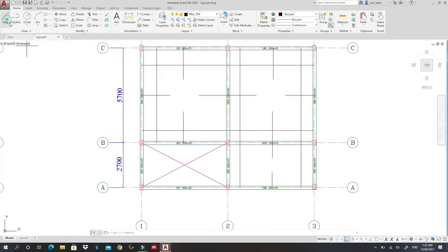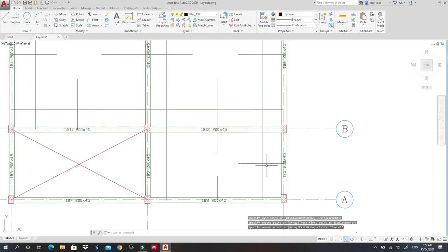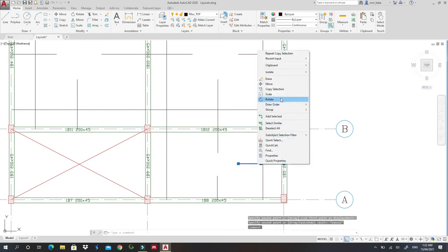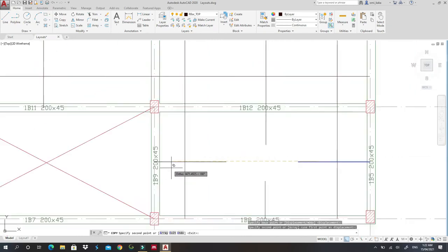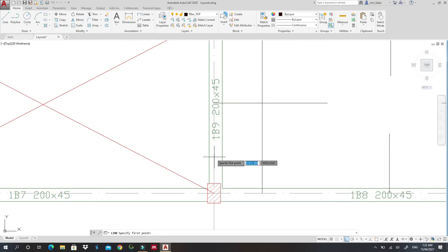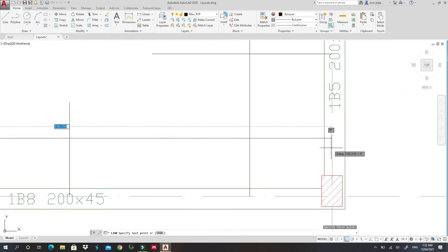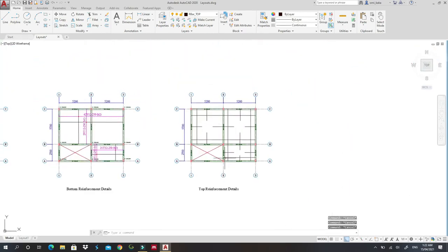Okay, the next thing is to put a bar here, which should be the length of this one. So I can just copy this and I will paste it right here. And also I can take, because it's the same panel and there's no slab, I should do like this. Okay, and lastly I can draw another bar, which is the last bar for top reinforcement, this one. Okay, so this is the arrangement of my top bars, and as you can see, there will be no reinforcement at the center here.